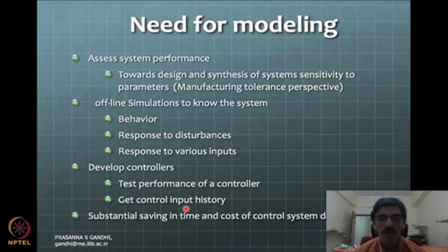We talk about those things a whole lot in an automatic control course. But nobody cares about what input I need to maintain a certain performance for the system. That is a very important aspect in the practical world, because your input is always limited. You'll have a saturation on your motor input or motor power, and that needs to be factored into your simulation studies.